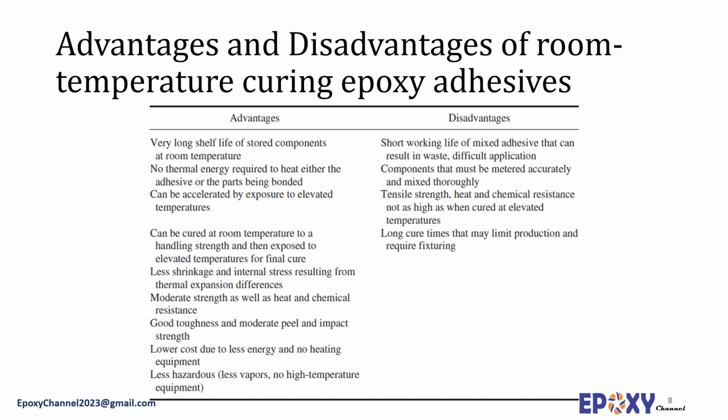However, during the application, they show short pot lives. This means that the adhesive has to be prepared and applied in small quantities, which makes their application tedious for the worker. Otherwise, the wastage is huge. In addition, their metering is also crucial. If higher temperature is applied for their cure, mechanical and chemical resistance of these systems is affected. Finally, their curing might be time-consuming.